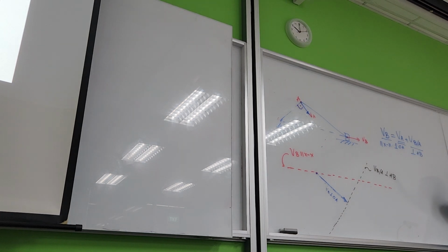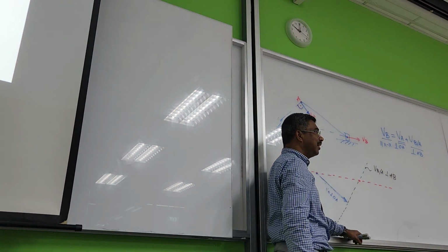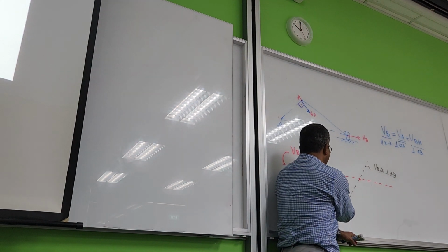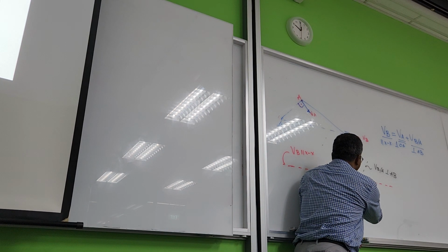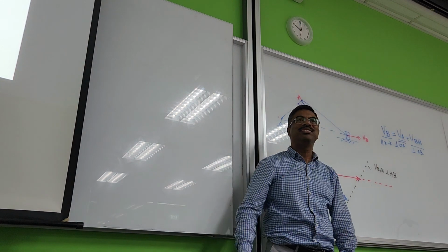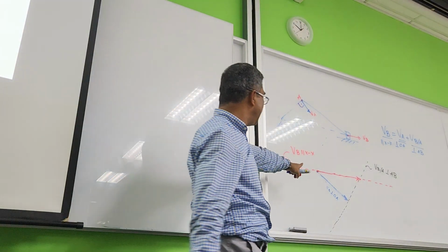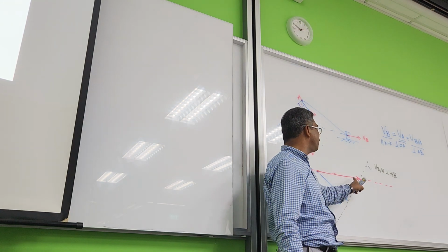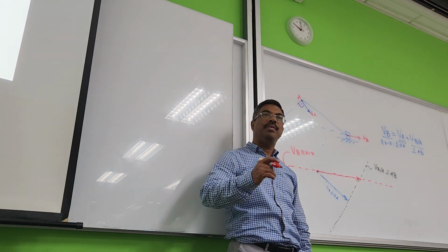So now I say, aha, I found the bingo. How? Look at what I am doing, because that is the interesting point. They intersect, right? I take this dotted line and make it a continuous line up to this point, and I finish my arrow. The dotted line now becomes a continuous line, and this is my real length of BB.